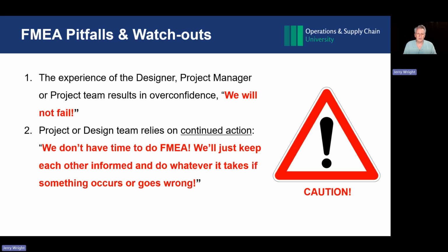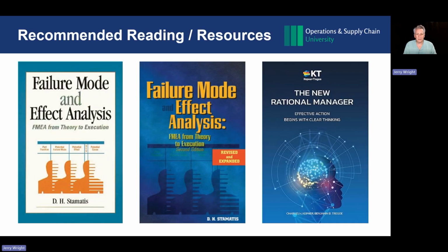It really doesn't take very much time to do the FMEA. And in some regulated environments like the FAA and the FDA, they expect you to do failure modes effects analysis. It's a requirement to submit products or different types of things for approval by those agencies. So it's not just a nice to have, it's an expected must. So again, you have a great way to go through this failure modes effects analysis if you've never done one before. They're pretty easy.